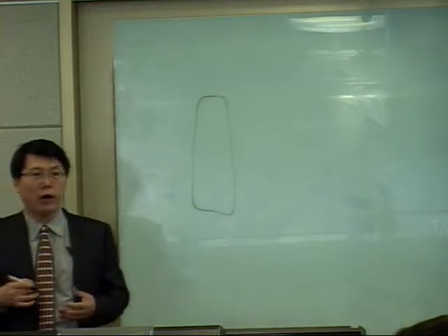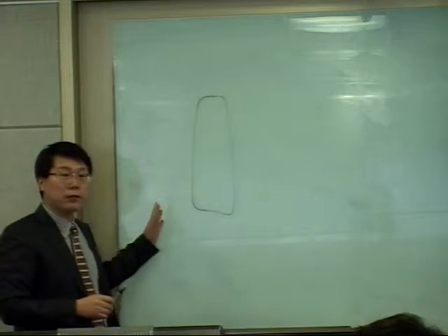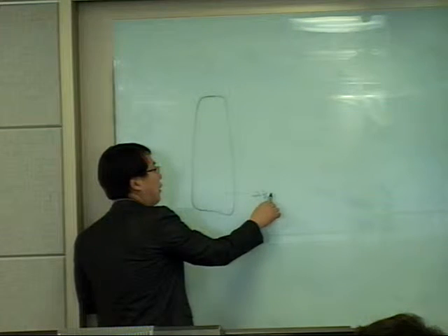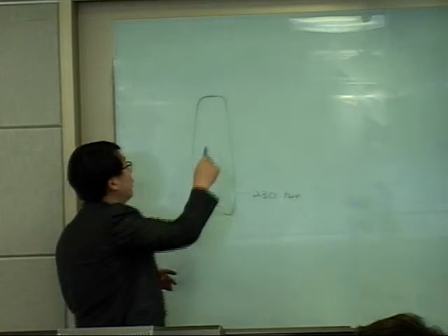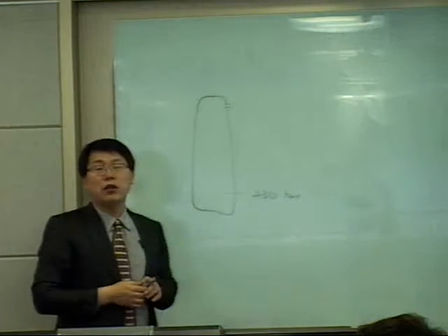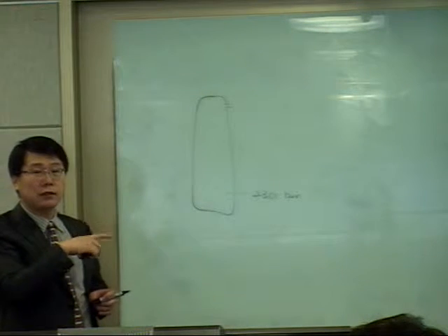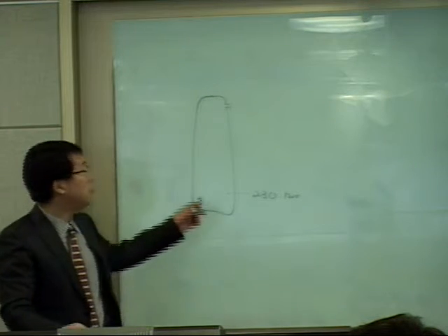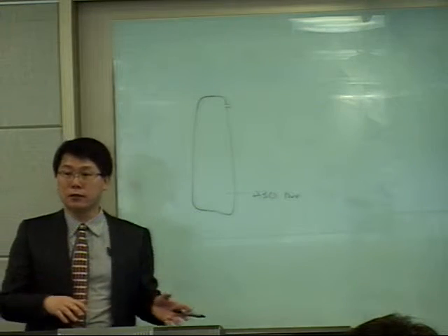CNG carriers require a pressure vessel. Assume that the original pressure is 230 bar, and there is a leak. Then, in order to solve this situation, you should consider this equation, and because the internal pressure is changing, the density will change and be time dependent.